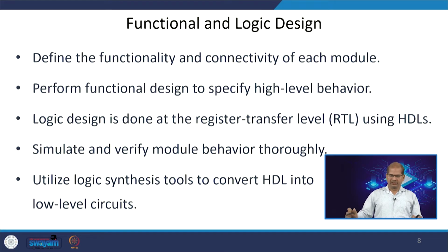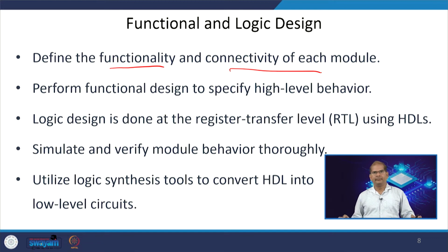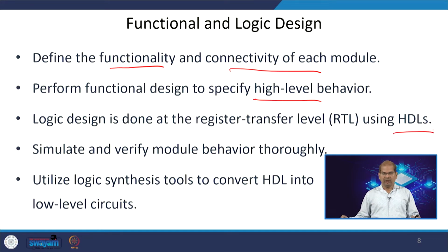Here the functionality needs to be satisfied, and the connectivity of the modules needs to be defined. Whenever we do the RTL, we need to simulate it multiple times, to check whether it is working at each and every point of requirement.